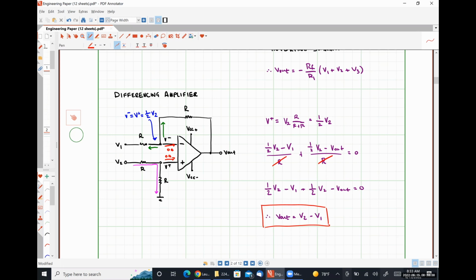We cannot perform multiplication and division of input signals using just op amps, especially not a single op amp stage. Okay, so that kind of stuff will be talked about later. But what we can do is actually apply calculus to input signals using single stage op amps. We can provide both differentiation and integration.